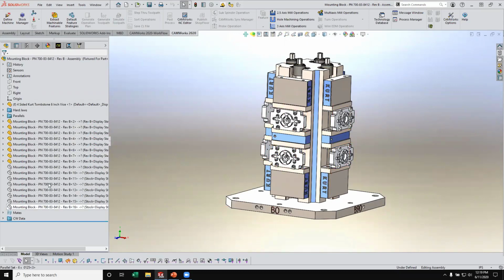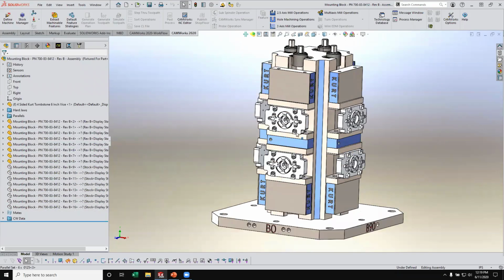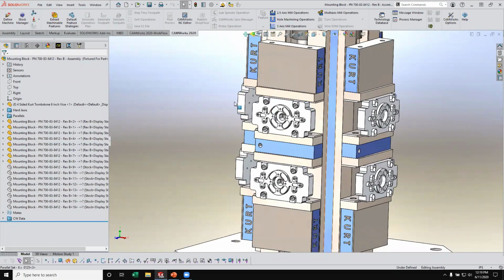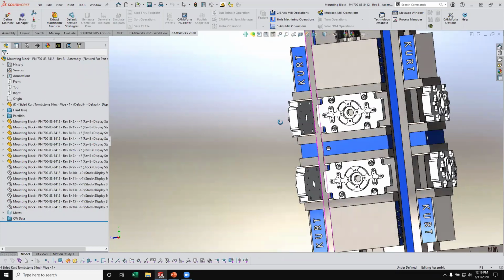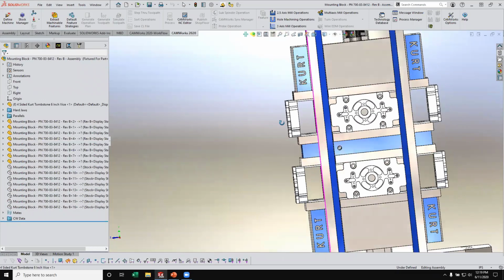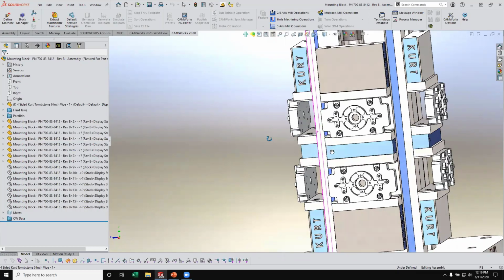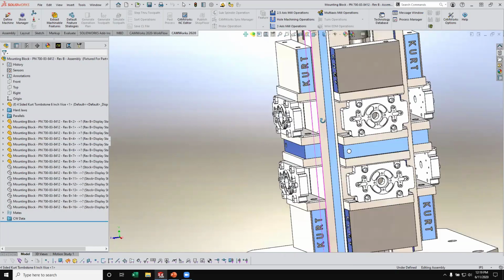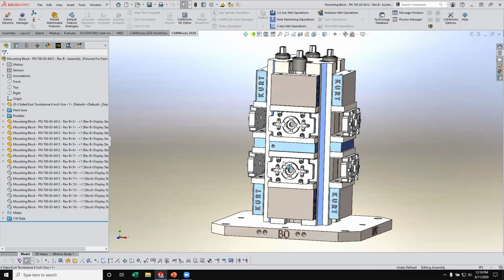You can see I have different features here through my assembly. I have the part in here 4 times, and I have a model of the stock as well in here, and that's because I'm going to have this stock already kind of squared up in that perimeter machine on a pre-stage before we hit the tombstone to mass produce these out by getting all the details in that one face setup that you see. Okay, so you'll see a bunch of holes and stuff like that in there.